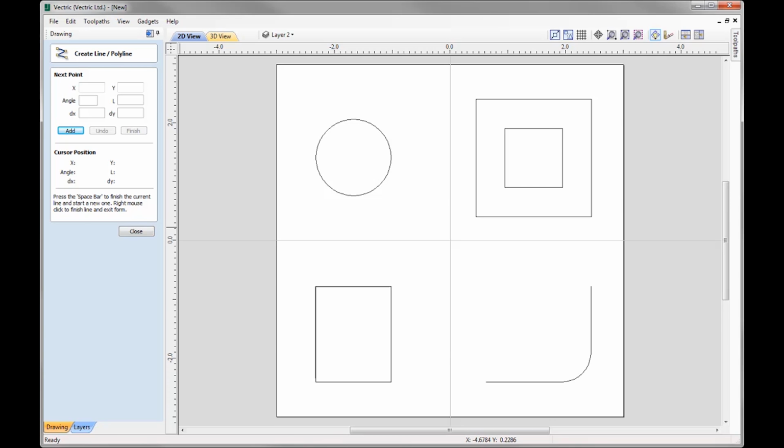Now if I wanted to create another square that was between the two squares, all I'd have to do is simply come over, wake this point up here, wake this point up here. Then as I come back, you'll see I'm now displayed an olive green line, and you'll see my cursor's change. It's telling us that we have now found a connecting line. If I follow that along, you'll see I now have a snap point. That's telling me that this is the dead center of the 2 points that you just woken up. And I can click that to begin creating my shape.